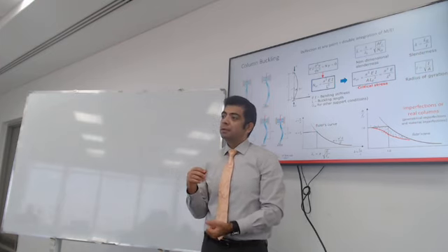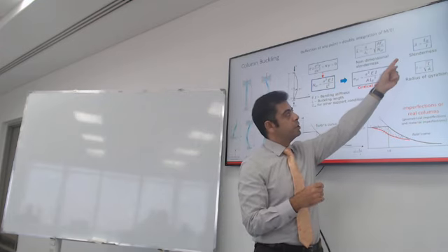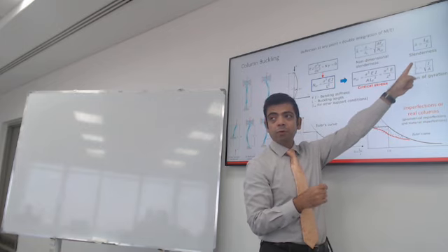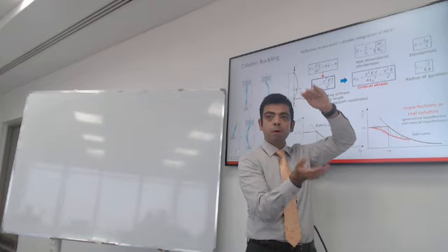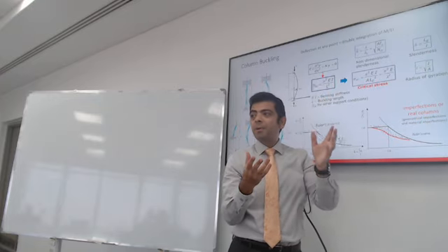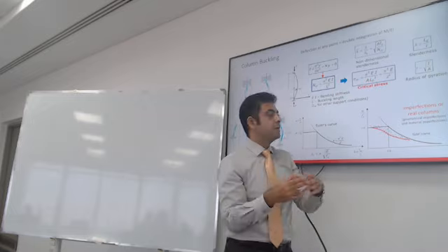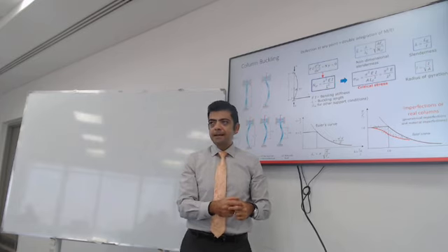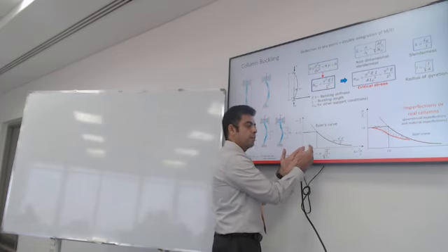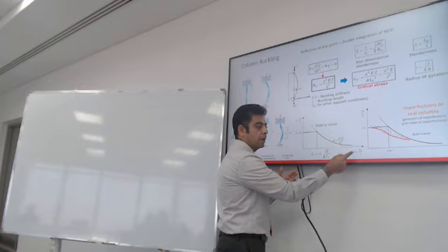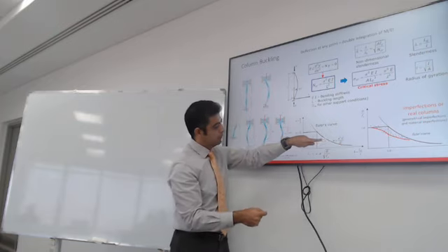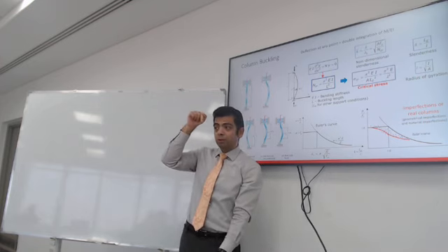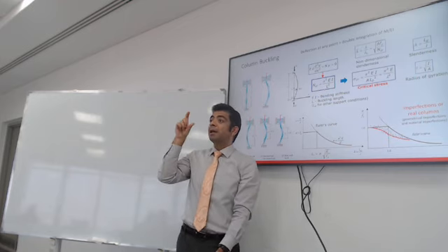The ratio between the length and the dimension. It's the ratio between the length and the ratio between inertia and area. So the radius of gyration is just the square root of the moment of inertia divided by the area. It only depends on the dimensions of the cross section. So you can say that lambda is the ratio between the length and the dimensions of the cross section. The bigger lambda is, the smaller the critical load is. So if your column is longer, very long, the critical load becomes smaller. So it can support less capacity.